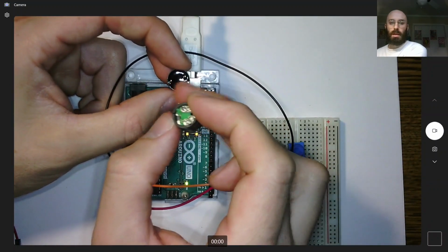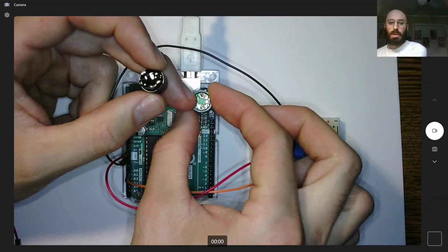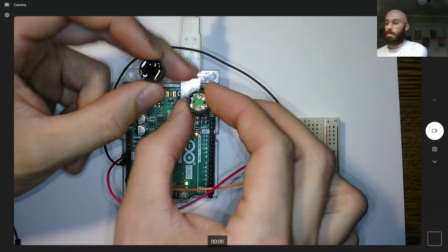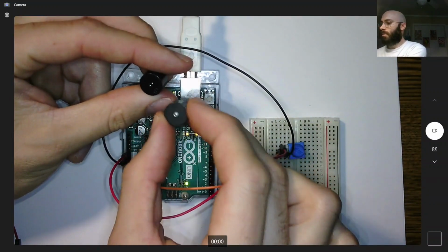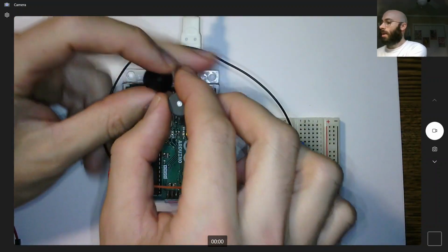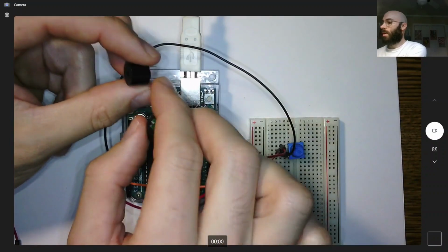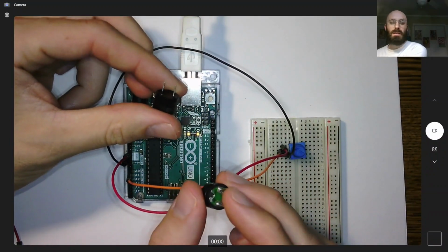One has this black potting on the other side, and on the other one you can see there's a bare PCB. Sometimes it's green, sometimes it's blue. But they both have polarity. They both have a pin that is labeled as plus on the top side there. And the difference between these two is this one here is something known as an active buzzer, where